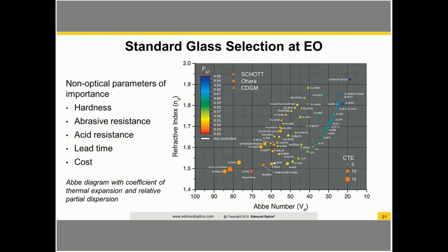We deposit slurry to soften the surface, and that's the chemical process that we're counting on to accelerate the manufacturing process. But if the material has a very high acid resistance, it results in a longer time for us to process the material, and therefore the cost goes up.